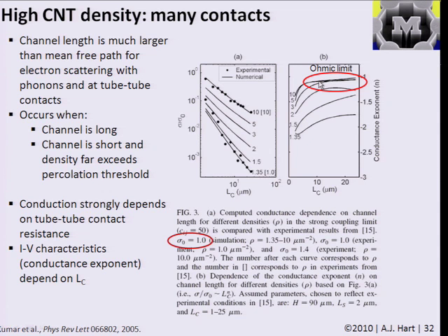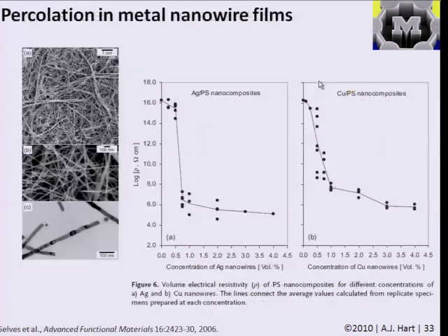And between those regimes, exact issues of the geometry and the topology are going to tell you how this scaling varies precisely with the number of contacts. But for example, if you could engineer the film so it had a very low percolation threshold, you might be able to create a more effective composite that could provide the conductivity necessary for electrostatic discharge at a very low volume fraction of fillers.